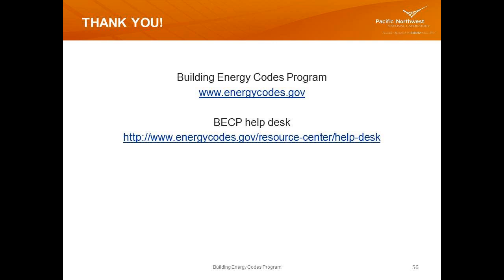Let me look at this next one here. Can lighting and HVAC be submitted as a default? In other words, only input the envelope data. As I mentioned before, you do not have to do each one of the provisions in COMcheck. I can do just envelope and be done with my project. I can enter just lighting and be done with lighting. So you don't have to do all of them at once.